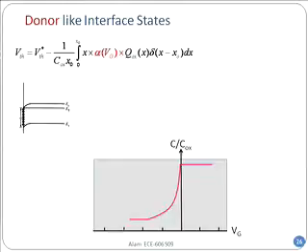Now I have bent the band, I have applied a positive bias. So now the N substrate is in accumulation, because it has brought closer to it all the electrons, the majority carrier. Now all the defect levels are below the Fermi level. They are all full. If they are all full, what is the total amount of charge? Zero. Donor levels all full, below the Fermi level, zero charge. If it is zero charge, then of course I have whatever my classical standard CV characteristic is, no problem. If it stayed zero throughout the voltage swings, then I would have this ideal red CV characteristic.